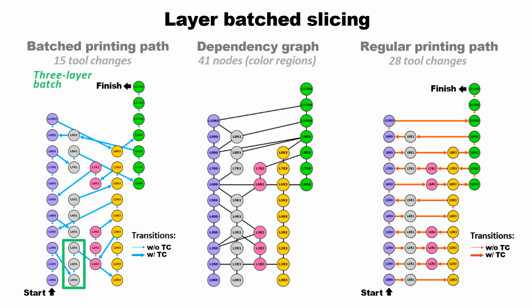If the number of layers in the batch exceeds the batch number specified at the beginning, or it is physically impossible to fabricate the next region without completing the other regions below due to region intersection, we make a random jump to another color and continue the process again.